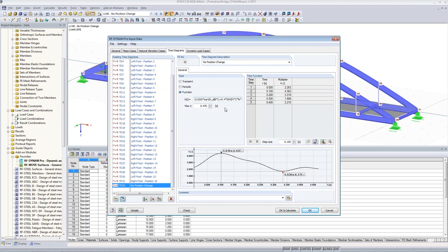And now, so far, we only considered one period of one foot. So now it's several persons going along. And so I would at least consider 2 periods here. So I would increase the max t to 1 second, or you can even study this a bit longer. But 1 second at least means we have both feet on the ground.